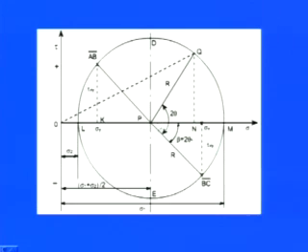First of all, you need to rotate these things by 2 theta, because we know that tan 2 theta p is nothing but equal to (sigma x minus sigma y) divided by 2 tau xy. So you see here, the 2 theta p can be easily rotated. So you need to rotate these things. So now it is rotated.